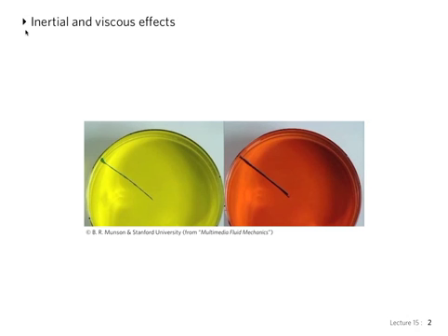So we were discussing at the end of last class this sort of competition, if you will, between inertial and viscous effects. And I showed you these two movies where on the right you have this orange fluid, where at the moment you start rotating the container, the whole fluid starts moving with it because it's dragged on by its own viscous forces. So you have here the situation where the high viscosity of this fluid results in the viscous effects dominating the flow, and inertial effects somehow are negligible in comparison.